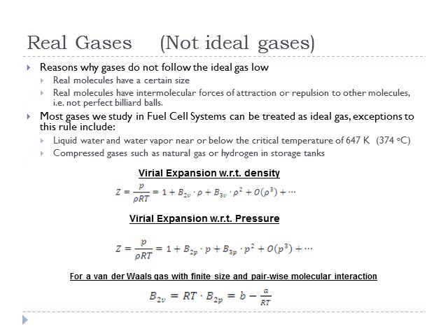Okay, so water vapor, you can see the critical temperature is really high compared to any other gas. And so unless you're at temperatures of like 800 to 1,000 Kelvin, which you'd be at, let's say, for a fuel cell, or when you're combusting, right? In a combustor, you can treat water vapor as an ideal gas. But water vapor in PEM fuel cells, you can't treat as an ideal gas.